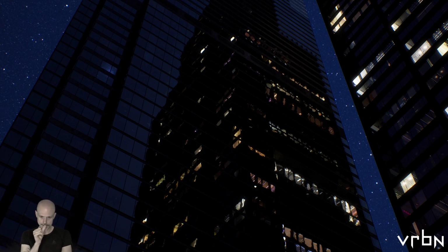But the point why we specifically wanted to test this is that even though you have reflections, which are ray traced here in Unreal, the challenge is that the parallax occlusion shader actually has to work geometrically correct even in reflections. So we have a big glass facade here, but the ray direction is first reflected in the skyscraper, and then it's showing the reflection of the virtual parallax occlusion interior on the other side of the building here. And all the vector math actually has to work completely correctly so that you don't get any weird distortions, right? So we needed to solve all of those things, and it works.